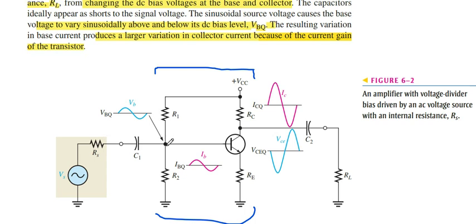If we read the voltage divider carefully, this point is A in the voltage divider. When we give the signal to point A using this capacitor, we get the output across the load resistance RL at that point, while C1 and C2 are the coupling capacitors, which are used to block the DC voltage.